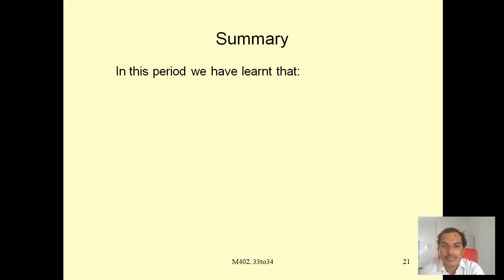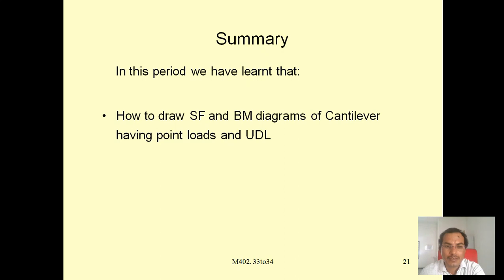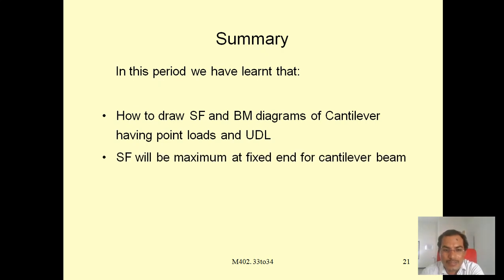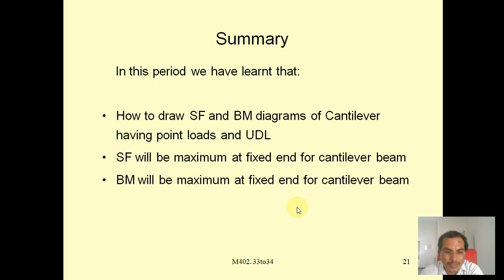In this period, we have discussed how to draw the shear force and bending moment diagrams of a cantilever beam having point loads and UDL load. The shear force will be maximum at the fixed end of the beam, and the bending moment will also be maximum at the fixed end of the cantilever beam.